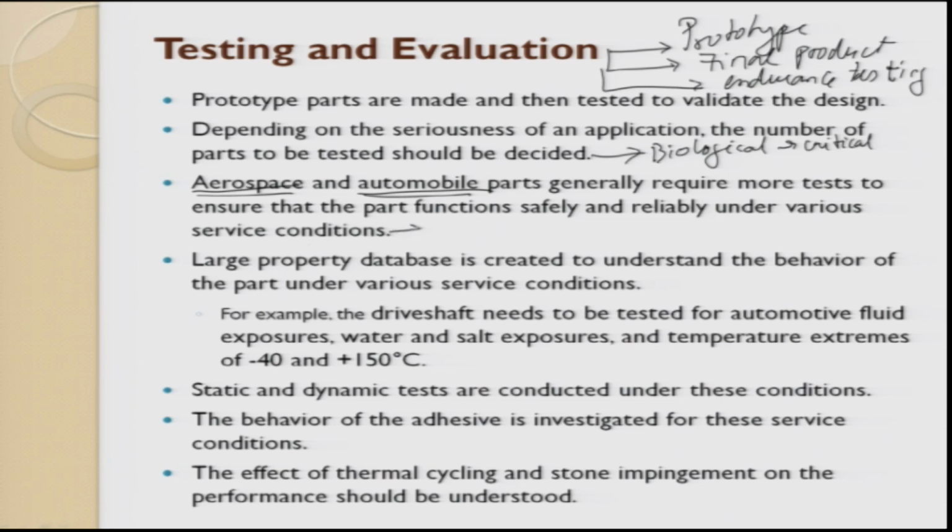So here the service conditions are, for aerospace, minus 50 degrees C to plus 50 degrees C, it has to work. Whereas when you talk about automobile, it generally works between, you can take it from 0, very rarely on minus, up to 50 degrees C. Maybe this can go up to 50 degrees C, because that is the atmospheric temperature we have, and sometimes it can be tested even at minus 10 degrees Celsius, whether the engine components work, the spark plug cranks, all these things can be done. So these are the service conditions, and it can be altitude also.